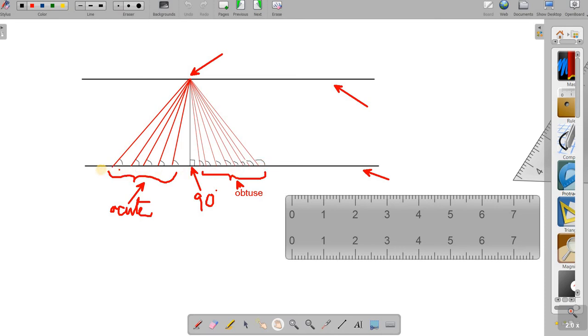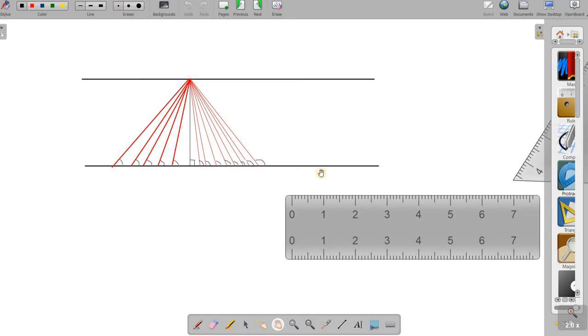So when we are asked to draw a line parallel to another given line, suppose this is the given line. I'll just change the cursor to something else. I'll show it to you in this mode. Suppose this is the given line, and this is the other line to be drawn. I just have to construct a perpendicular at any point on the line, and then another line which is perpendicular to this perpendicular will be parallel to the given line. So this is the concept, the idea behind drawing a line parallel to another given line.